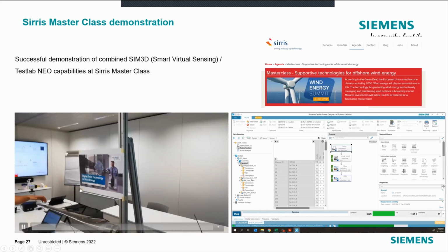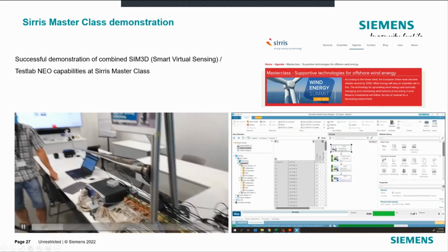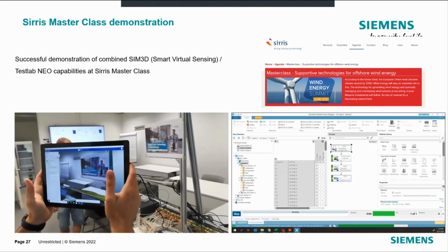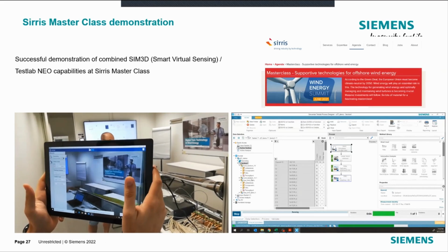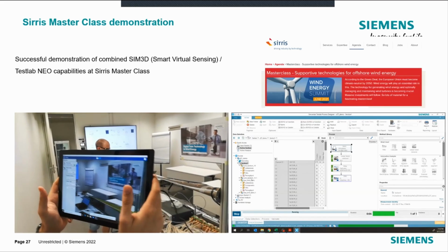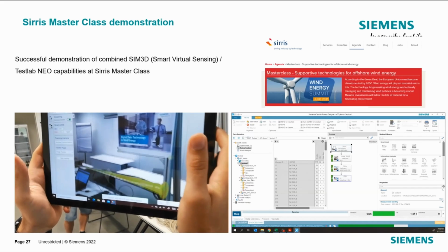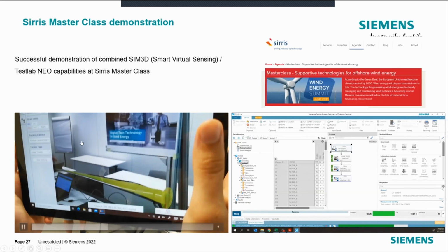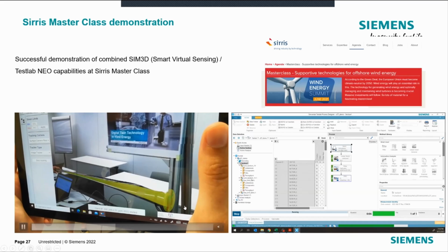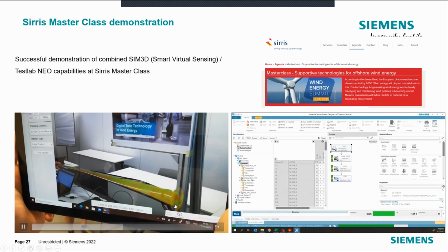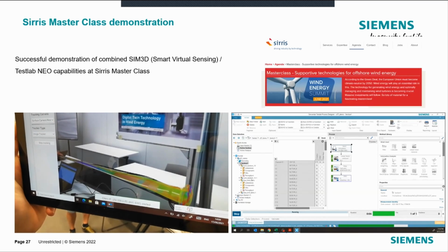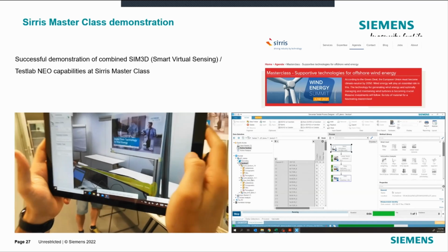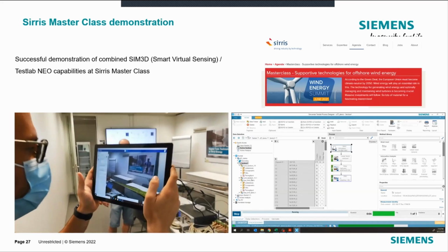And now you will see on the tablet a bit what I wanted to show. The video is moving a bit too much, but overall, here you see the physical blade, and the digital twin of the blade itself is also there. Now the guy will be pushing on the tip of the blade, and then you will see the strain field. Here it's not very visible, but here you see it a bit more. So here we are plotting the strain field on top of the real structure.